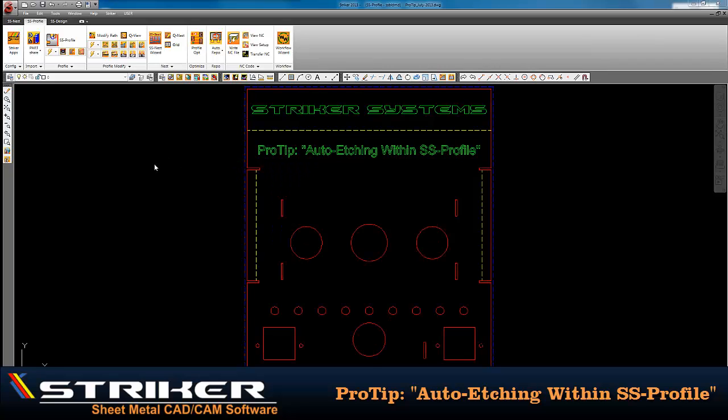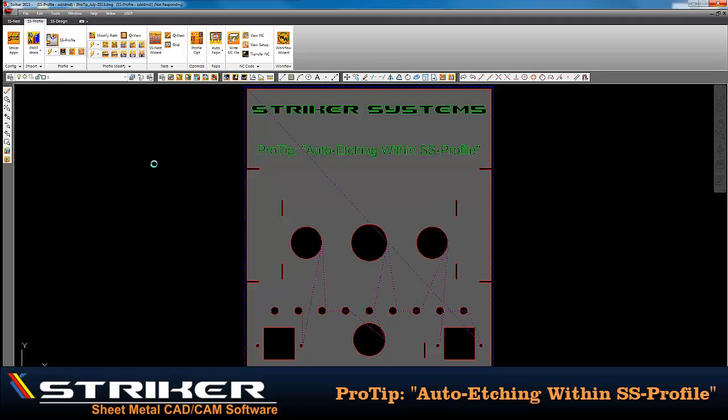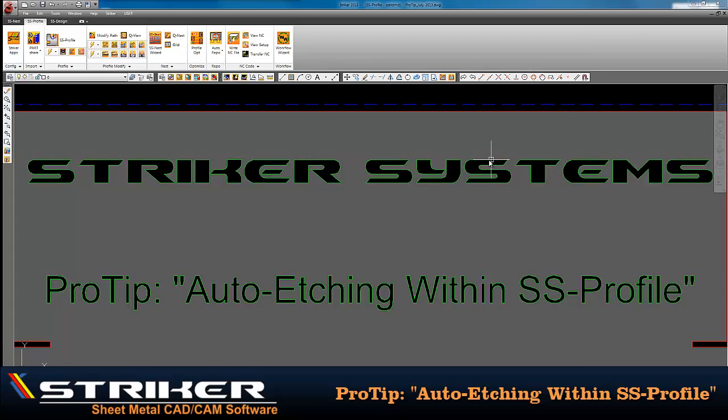As the geometry is processed, we can see how the objects located on layer 0 gets converted to the default pierce and cut process, shown in red, while the objects on my etch layer gets processed with my etching tech tables, which appears green. With the etch layer saved into a template, the layer process control set up to automatically etch any objects on that layer, I can simply move any future geometry to that etch layer prior to running my auto processing command to have the system automatically split out the two processes for me.